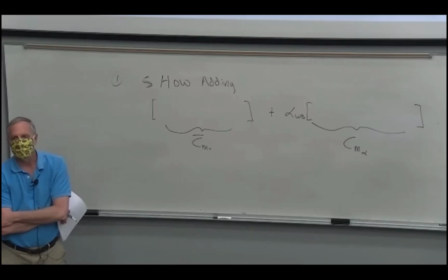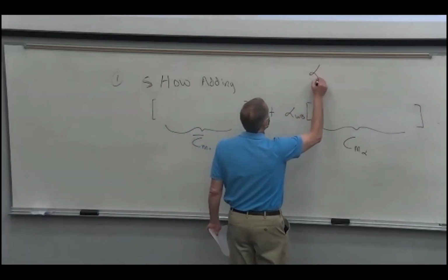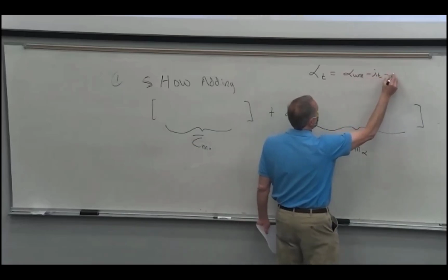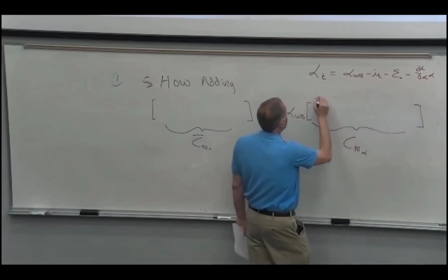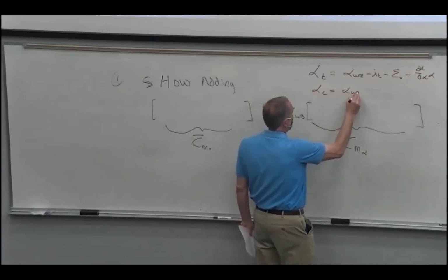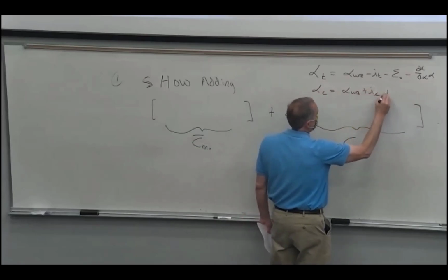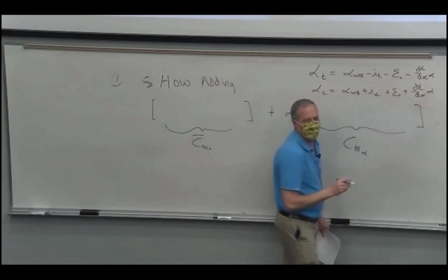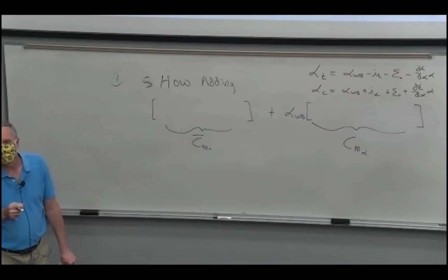And it's plus epsilon 0 rather than minus. It's because for the angle of attack of the horizontal tail, it's alpha wing body minus IT minus epsilon 0 minus d epsilon d alpha times alpha. And for the canard, we identify IC as positive up, and then we say it's upwash rather than downwash. So I think that should account for the differences in the signs. Make sense?